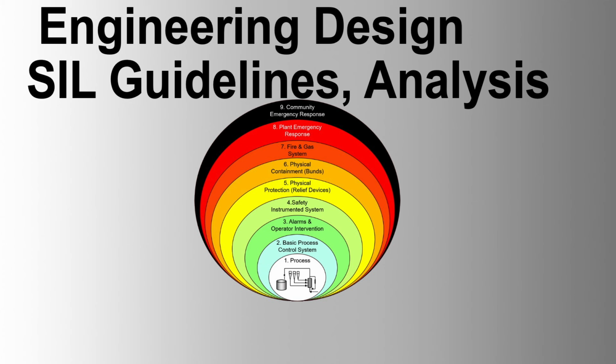Base example, common across parts of TR84.02, demonstrating the procedure and technique for calculating SIS PFDAVG and MTTF spurious. The Markov analysis technique provides a comprehensive method for evaluating the reliability and safety integrity of safety instrumented systems, accommodating various failure modes, repair strategies, and diagnostic capabilities.